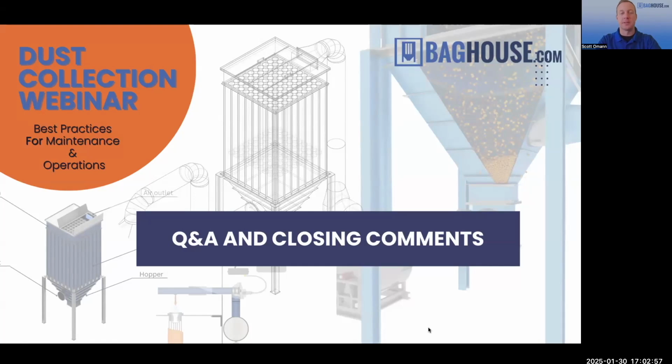Yeah, sometimes people think that the hopper is supposed to be full, or that there's supposed to be material always within the hopper. The hopper is obviously designed to collect the dust, and it does fulfill that purpose, but only on a very temporary timeline, only until it can be released through the airlock. Some places we go to, you open up the dirty side, and where the hopper is, it just spills dust. That's a huge hazard if it's anything that could start on fire. And if the dust is accumulating so much within that hopper, it's not allowing the air to go through that airlock to be discharged correctly.